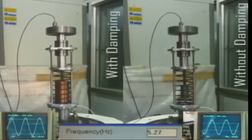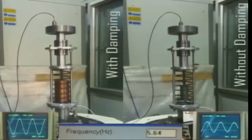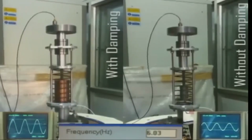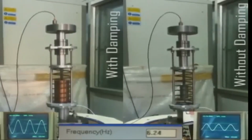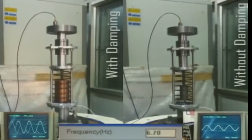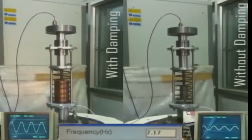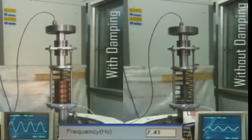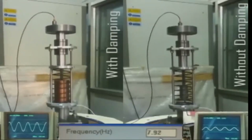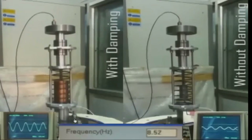Look at the right hand side and see how vigorous the oscillation is. If you look at the top plate, and you can also see it in the oscilloscope. And if you look at the left hand side, you would see that most of the vibrating energy is getting transferred to electrical energy, and hence you get much less vibration amplitude in the left hand side case. So, that is typically what you will see in a system which has a damper in it. In this case, the specific damper is called an eddy current damper, and the frequency of damping is around 8 hertz. So, it is between 7 to 8 hertz that you would see it.